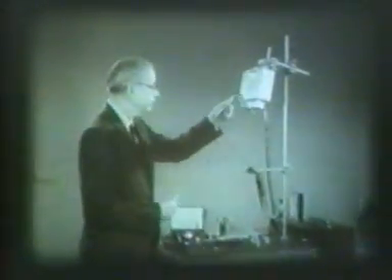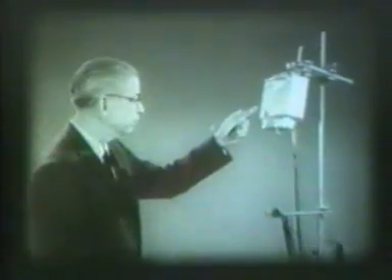This box contains our light source. The light comes in bursts, about 3 times a second, from a xenon flash tube. We can look at the intensity of this light as a function of time by allowing some of it to fall on this photocell and displaying the photocell response on the oscilloscope.